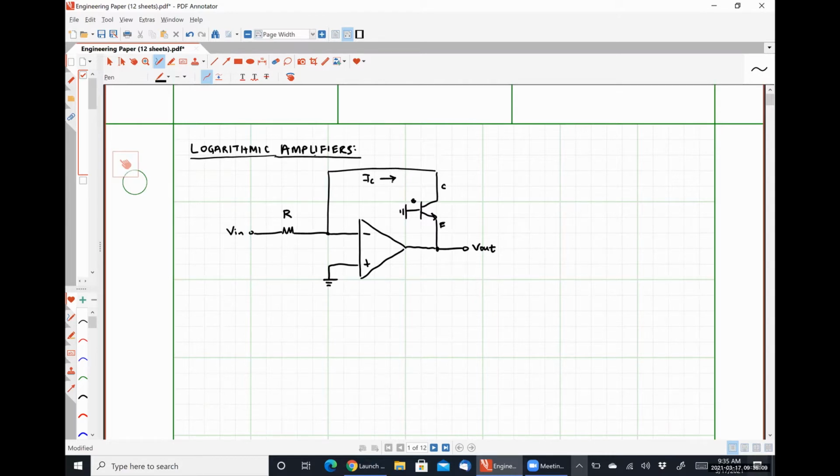All right. So let's first look at this with an ideal, or infinite, open loop gain. Dang it, my stupid thumb's getting in the way. So when A naught is equal to infinity, what that means is that the voltage here at node X is equal to 0, because there's no difference between the non-inverting input voltage and the inverting input voltage.